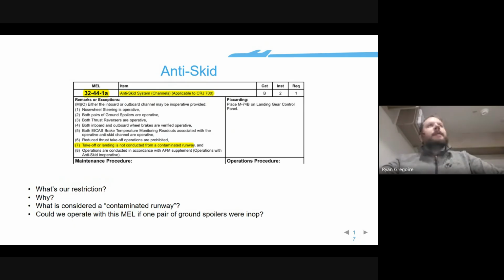When we're talking about what is the max takeoff weight for the CRJ 700, or what is the max landing weight for the CRJ 700, when we're talking about those numbers in the context of aircraft systems, that is the maximum structural landing weight of the aircraft, or the maximum structural takeoff weight of the aircraft. That is saying that all other factors being negated, that's the heaviest the aircraft can structurally handle taking off or structurally handle landing.